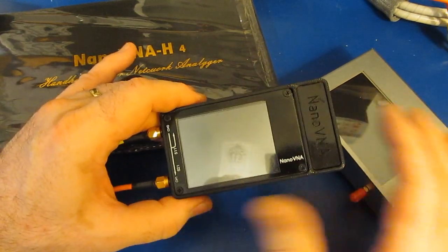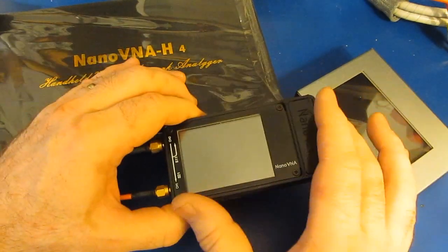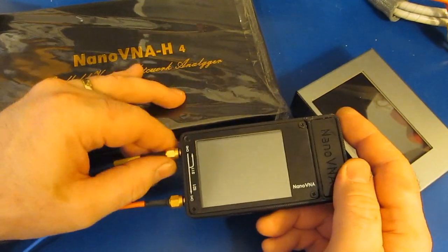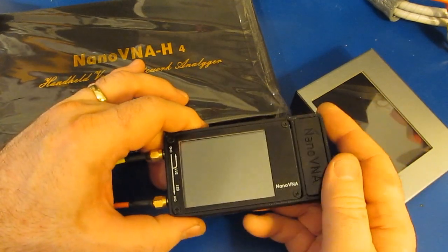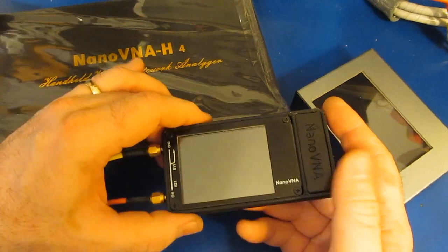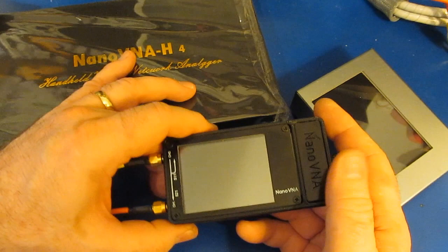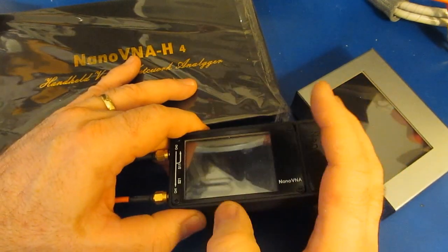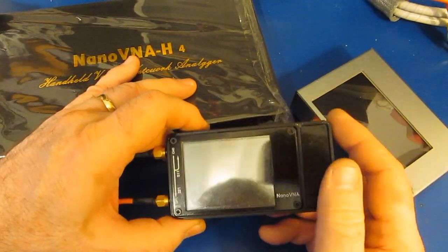And of course, for a high-speed digital design, we'd also like to look at high frequency. Our circuit board may only have a clock rate of even 10 megahertz, but typically for EMI, we have to test well above a gigahertz. So it's very possible that the designer is interested in making measurements well above the clock rate of the board that they're testing.